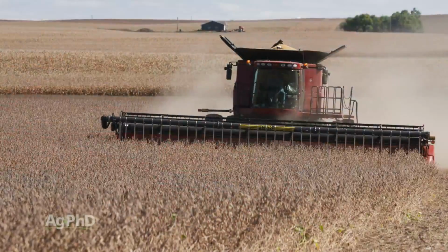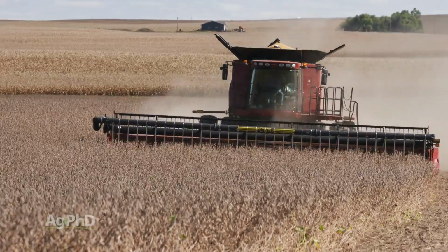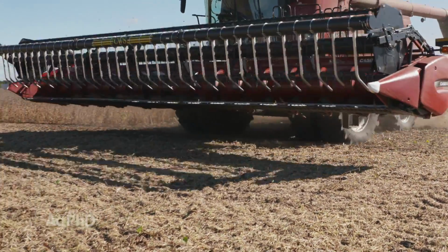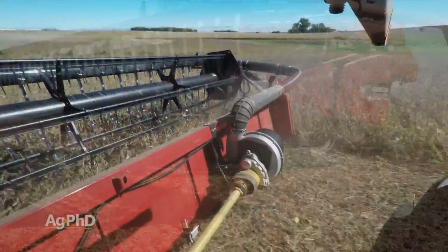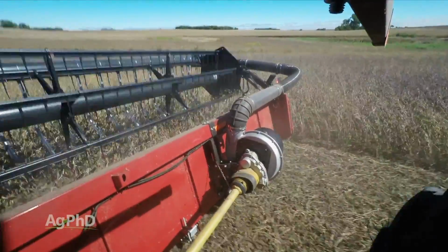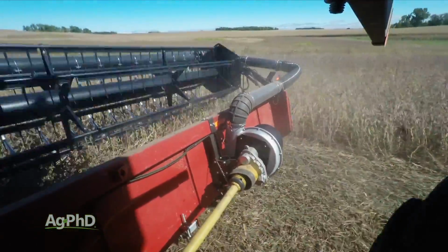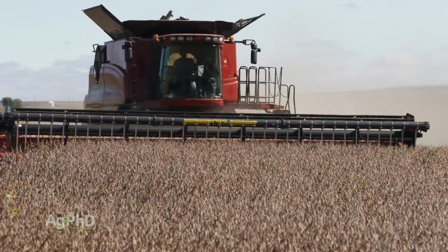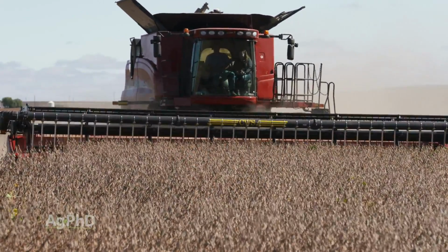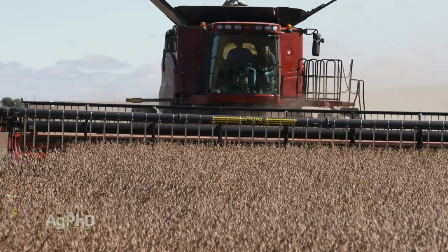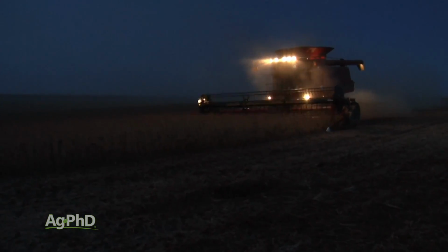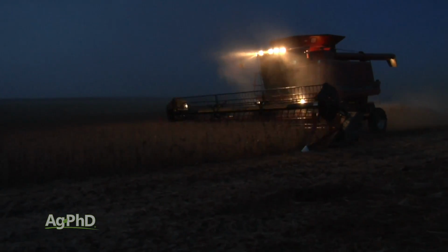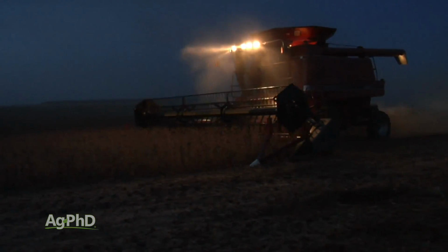Now, on our farm, we've been running air reels for years. The key advantage is getting soybeans to feed into the head evenly rather than bunching up. Farmers using these types of systems are able to thresh much more efficiently without loss at the head. As harvest gets rolling across the Midwest, here's one other huge benefit that you'll see with air reels and farms that are running them. You can get started earlier in the day, and you can often run later into the night. This became a noticeable advantage in areas where weather became a challenge last fall, and it's playing out at the beginning of this season as well.